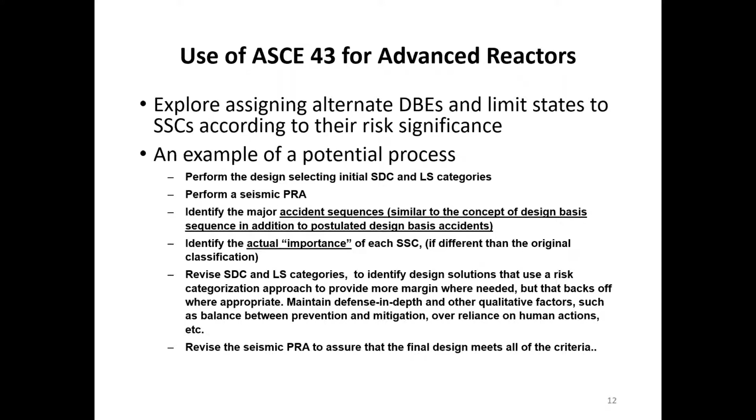I want to add one thing and not give a wrong impression. You would not do these SSC for every structure, system, and component. Generally, in practical settings, it will be done based on groupings, and we already have some experience with that kind of thing in the light water reactors through the 50.69 process, where we have grouped SSCs in different risk categories.